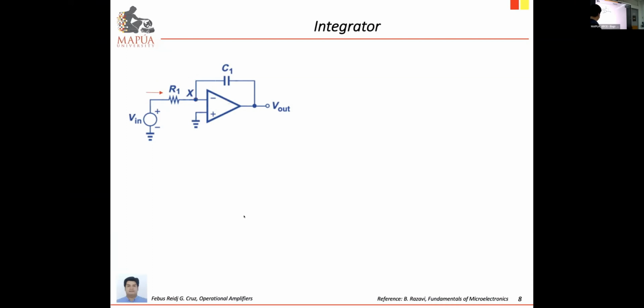Right, so again, from the input, you have the input current. Okay, so you have the current along R1 equal to current along capacitor 1, then equal to Rin. Okay? So IR1 equals IC1 plus I in.